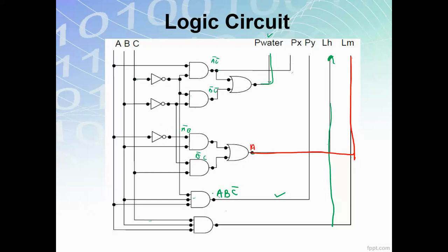Okay. So this is A bar B plus B bar C. Okay. And this is A bar C bar plus B bar C bar. Okay. Right. And then this ABC. So it means there are many outputs. So you have to make an individual K-map for each individual output. And once you have the K-map and the expressions, draw the circuit diagram based on the expression that you have simplified using the K-map just now. Okay.